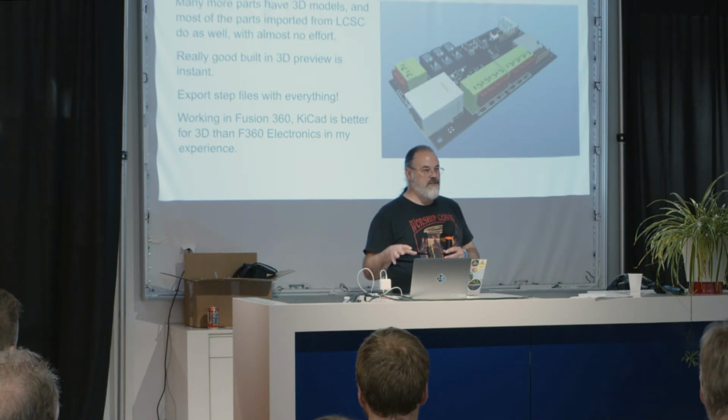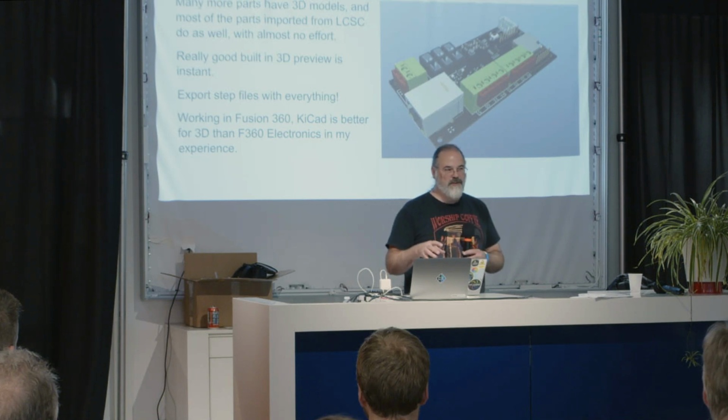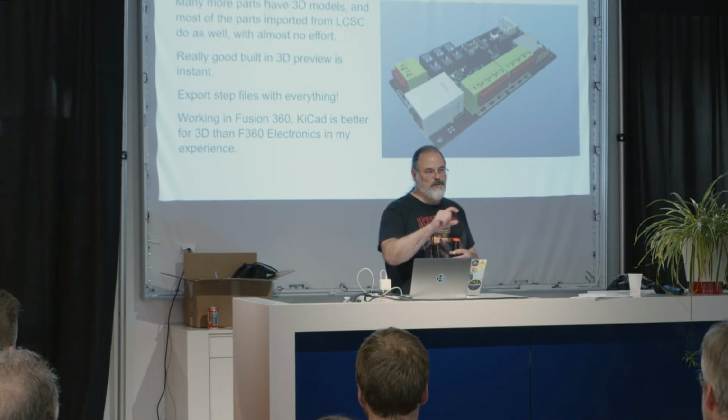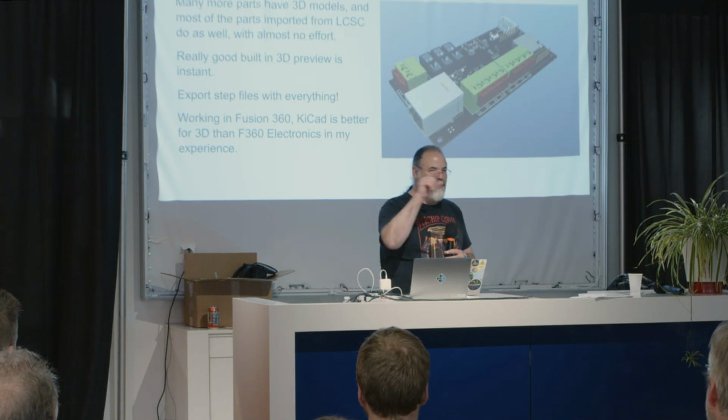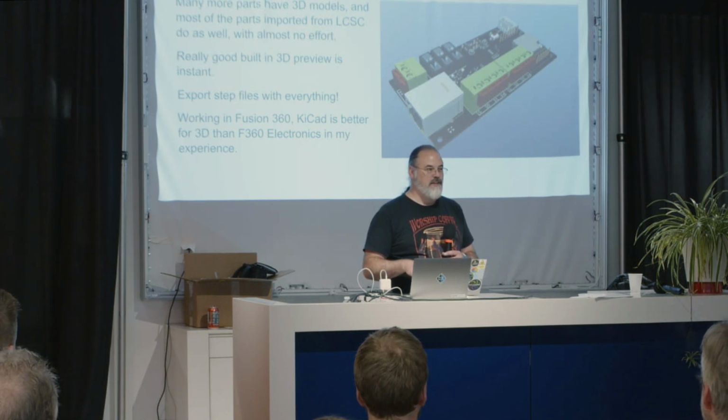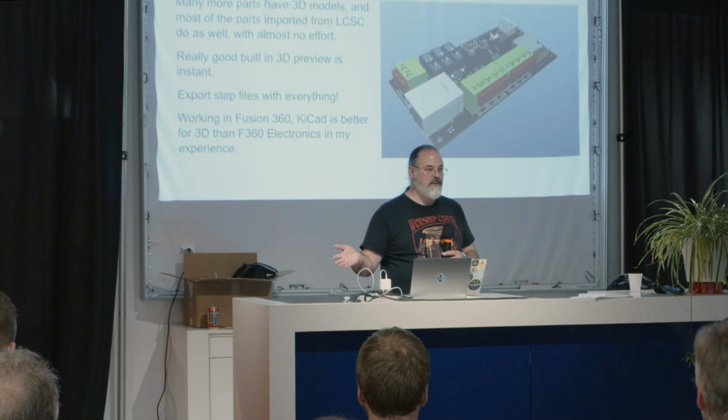And then if you make a change, like let's say you want to update that library and make sure that you have an actual footprint instead of just a weird little rectangle that doesn't look anything like it at all, there's like a million steps. You've got to update and save this. It's faster to just export a STEP file and import it again from KiCad. It's amazing.